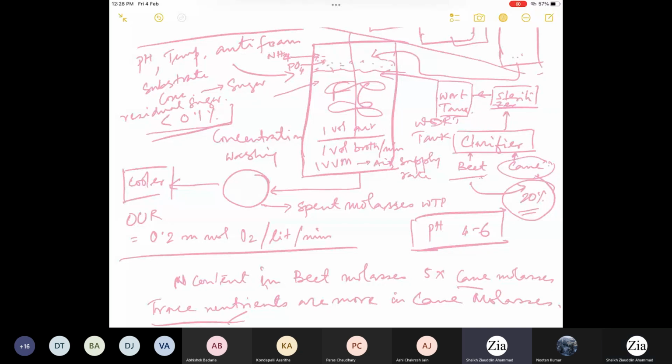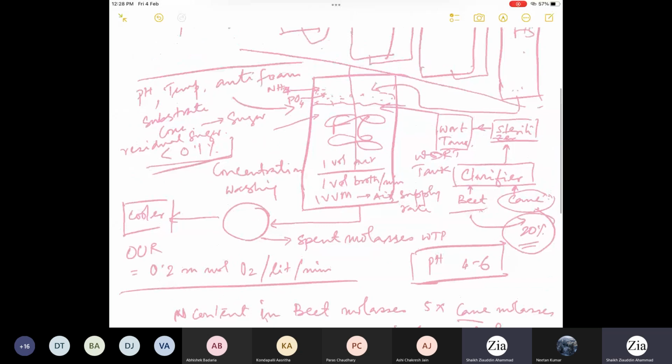Foam formation is not desired in any fermenter, because wherever you have foam, oxygen transfer from the dead space gas gets hindered, and the foam will also collect biomass present in the system. Whatever biomass goes to the top surface of the liquid automatically gets trapped in the foam. Also, effective exit of carbon dioxide is affected if you have foam formation on top.